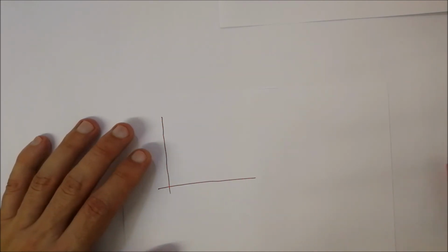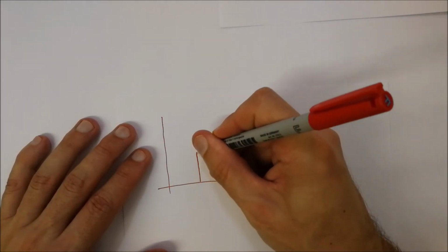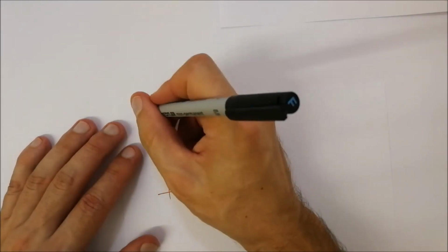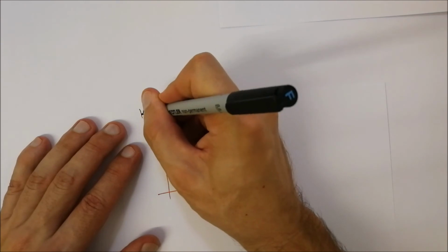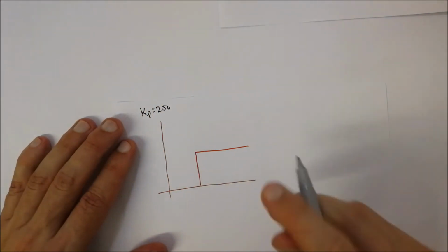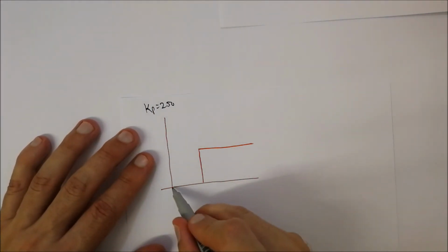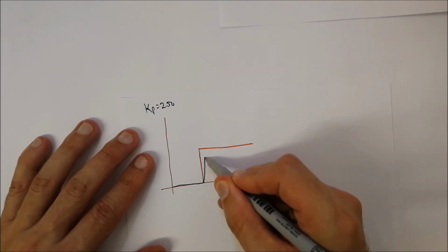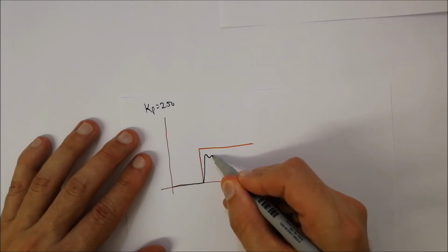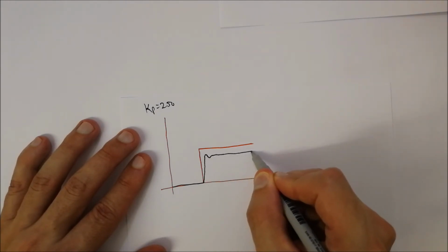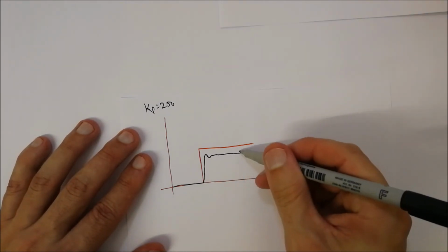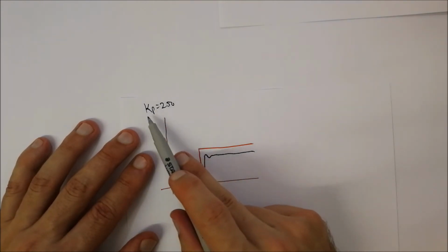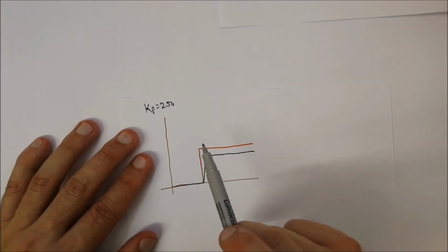As I showed you in the previous example, and again this is where you're going to have to do your tests, if you set Kp to 250, you might find that it's going to come over here, increase, oscillate over there, and then even out. It's not going to get to the set point that we want, and that could be because our Kp value is too small.